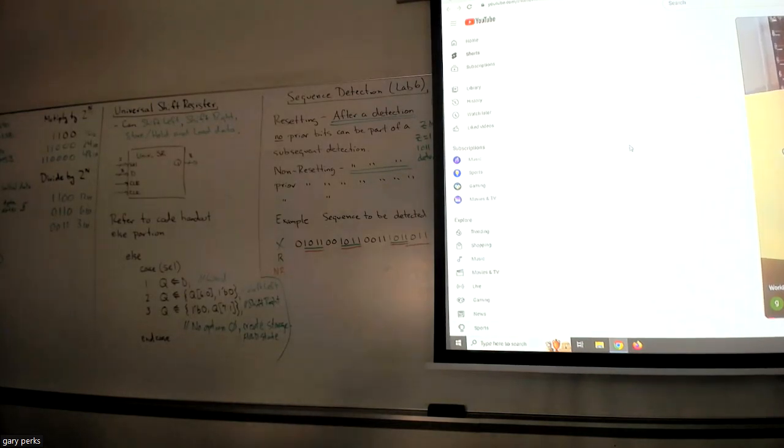Okay, so you see the LEDs are moving. As an LED lights up, that's the bit that's being inputted to your FSM. And I have the switches set for the sequence for when a button's not pressed. So after it goes through checking all the switches, it will change when it finds the sequence. And that sequence can be within any pattern of the 8 switches. Now I'm changing it so it's not the sequence that's being looked for with the button not pressed. So you see it just stays crap the whole time because it didn't pick up the sequence.